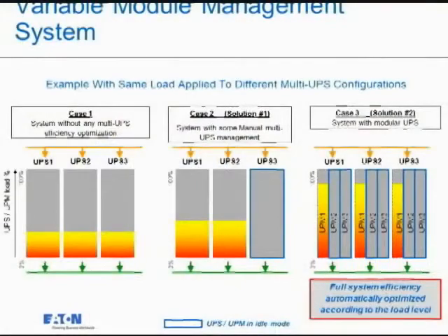So we took three 500 kVAs and we put them all together, and their loads subsequently went from 200 to 400 to 600 to 800, and then they went to blade server technology, virtualization, and all of this, and the loads decreased. So I met up with them last year, and basically we had three 500 kVAs. Their actual load requirement was about 300 kilowatts, roughly.